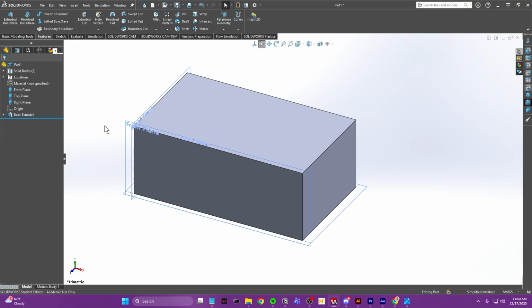To do this, I'm going to press the S button on my keyboard, and from there I'm going to access the Quick Shortcuts toolbar. From here, I have the option to disable the view planes. If this option does not show up for you, you can disable the view planes by coming up to the heads-up toolbar, where the eyeball is, pressing the drop-down menu, and then turning off view planes from here.